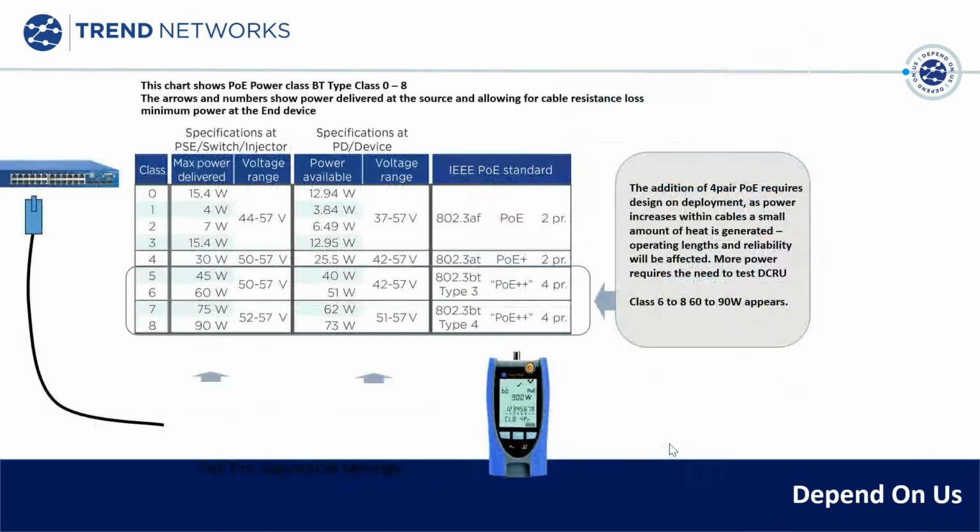So what is this load test? And what is this part two? If we've done our DCRU testing, and we've used the PoE Pro to first pull in the cables we've certified, and now it's live, and you're responsible for delivering the product, you're an integrator, you can now test your device for PoE delivery, whether you're doing a short run, a long run, or you may be taking a risk and doing an extended run. Let's go through some of these concepts.